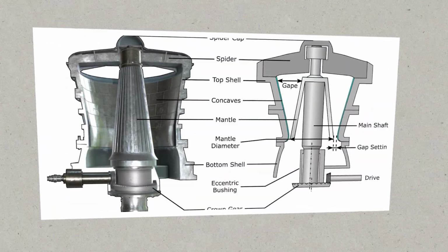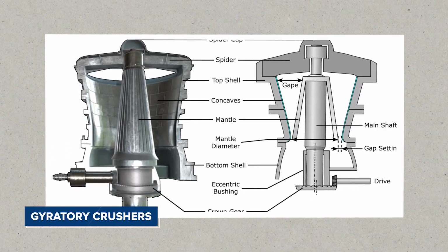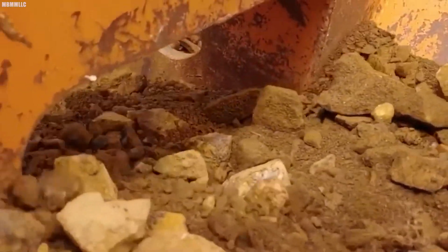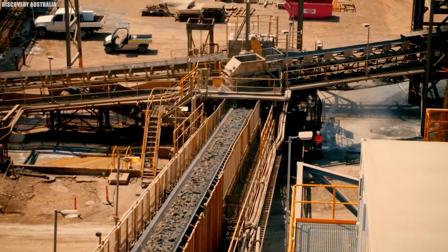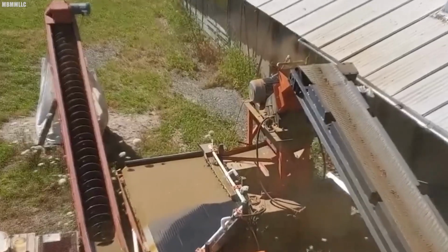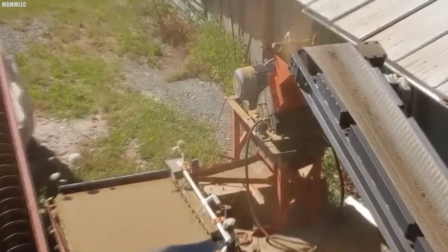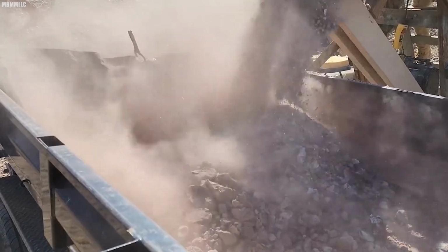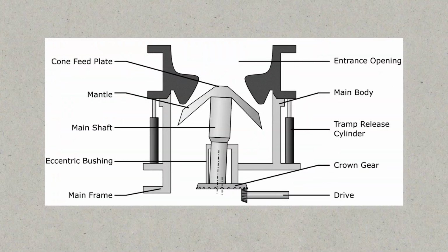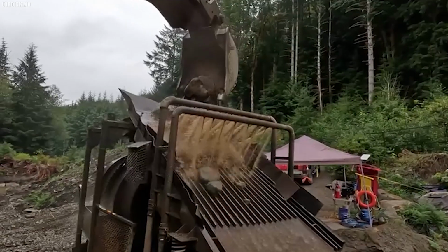Another option for primary crushing is gyratory crushers. These crushers utilize a gyrating spindle to crush the ore against a fixed outer shell. It's akin to a giant mortar and pestle. Then, more specialized than jaw crushers, cone crushers are used for secondary or tertiary crushing. They provide a more refined breakdown by squeezing the rock between an eccentrically gyrating spindle and a concave hopper.